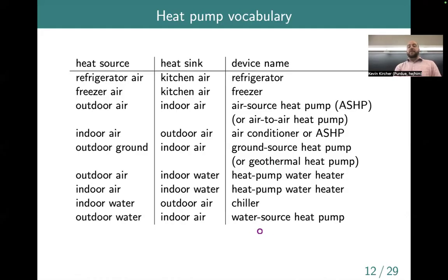The reason that improves efficiency is that in really cold weather it might be, say, 5 degrees Fahrenheit outside, but if you go down maybe 10 feet underground, it might be 40 or 50 Fahrenheit. Similarly, if you have a deep lake and you go down near the bottom, it might be 35 Fahrenheit or so, pretty much year round. So using that as the reservoir you're absorbing energy from, and thinking back to that COP curve, it's going to move your ratio T cold to T hot to the right and move the COP up.